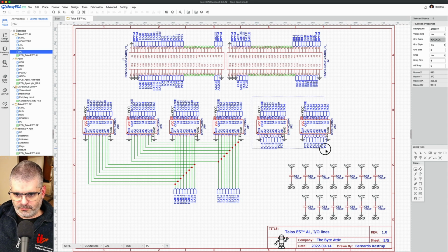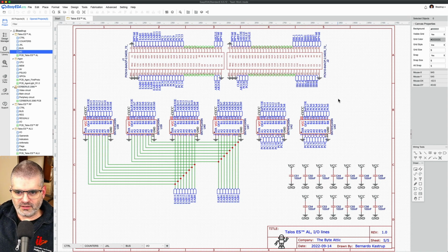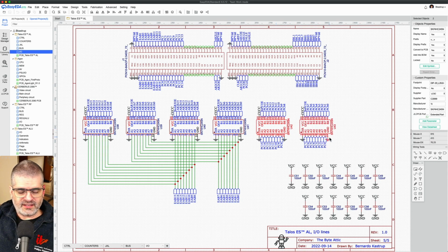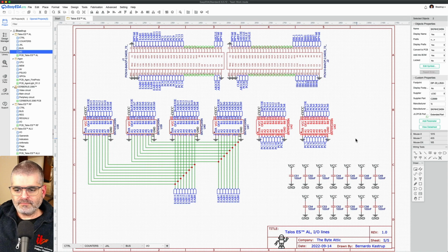That will decide which of these two pairs of buffers will be enabled and drive the external address bus. And regarding the program counter bus, only the program counter register can drive that bus, but I still put buffers there to provide some extra oomph to the signal just before it enters the backplane connector, not counting on the register chips to drive the line all the way across the backplane into another board. I decided to put these buffers there, and it has an extra reason. I should be able to tri-state these buffers based on this control signal, the program counter output enable, and that's crucial if I want to enable Talos to be DMA capable, to allow for direct memory access, because if the I/O controller wants to access the instruction memory to load the new application, then these two buffers here will be tri-stated, releasing the program counter bus for the I/O controller.